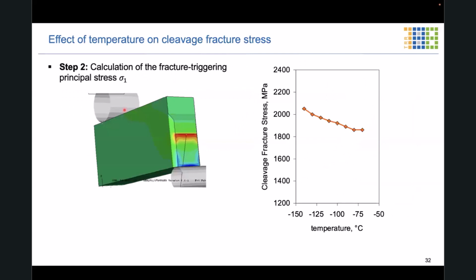So you perform those experiments and you measure the applied forces or displacements, and then you simulate the experiments with the help of the finite element method. And for the critical applied loads, usually expressed in terms of applied force or applied displacement, and for the spot for which you have observed the initiation of the cleavage fracture, you evaluate the applied tensile stress.